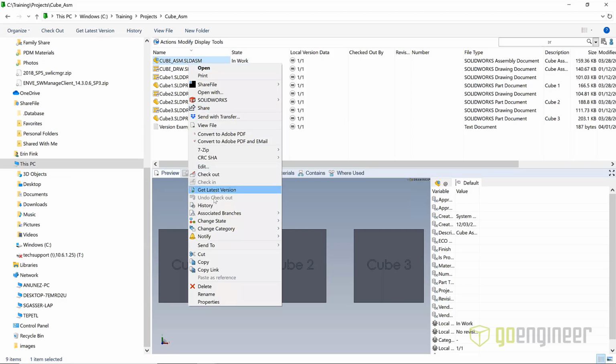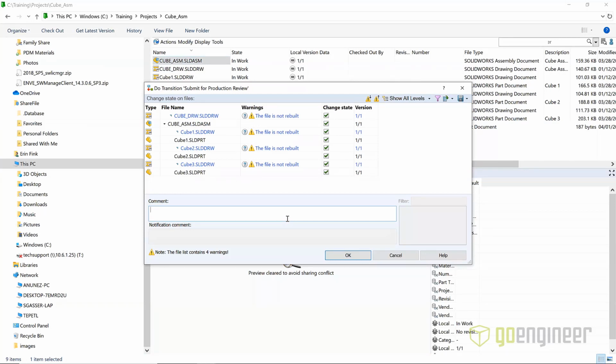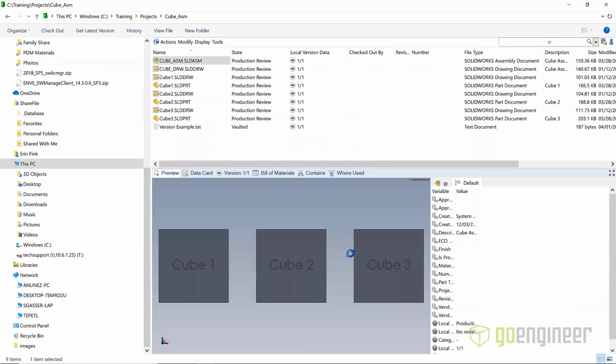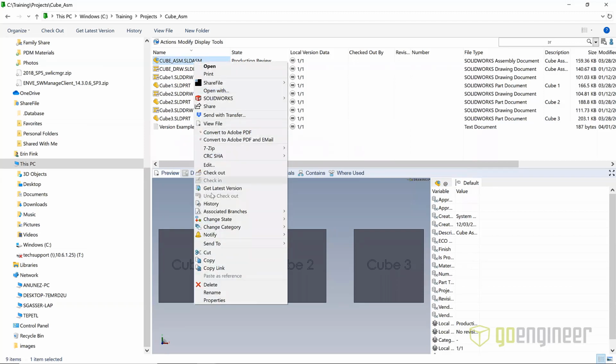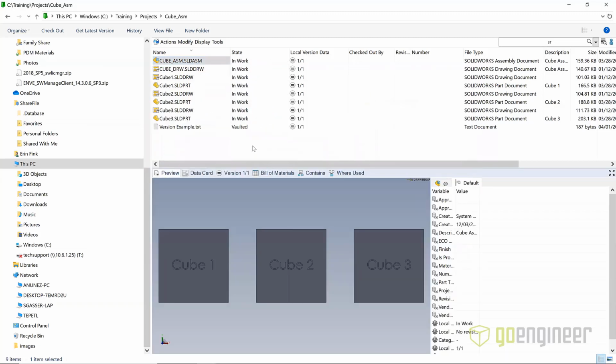And I can do what's called a state change in PDM, and this is to initiate files, and they can bring references with them to follow a preordained track. So this is a transition. I'm going to be submitting these files for review. And then from review, there would be options based on that workflow that the administrators have built in the background. So from a PDM perspective, as an approver, I'm going to say either change required or release to production. If I say change required, that would route these records back to in work.